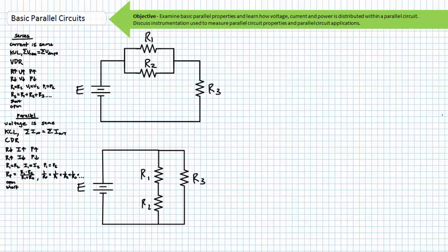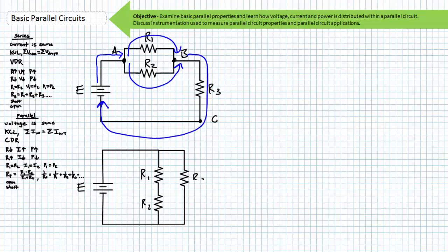What I've drawn here is two series parallel circuits. Let's consider a basic analysis of the top series parallel circuit using the perspective of flowing current. Source current leaving our source's positive terminal enters node A. At node A, current has a choice to travel through R1 or R2. R1 and R2 are clearly in parallel with one another. However, as the current from R1 and R2 recombine at node B, this single stream of current has no choice but to travel through R3 to get to node C and the negative terminal of our source.